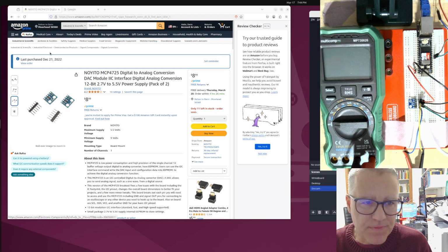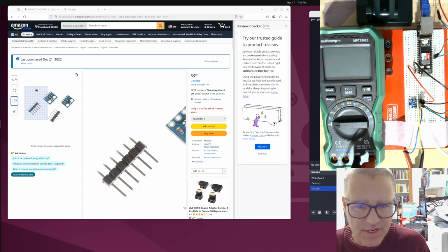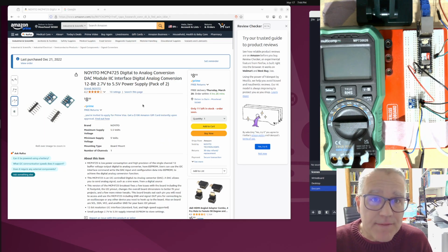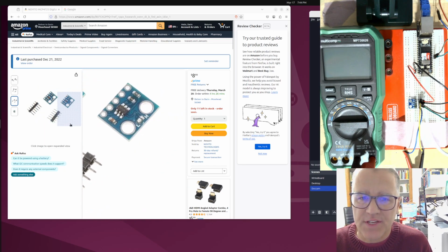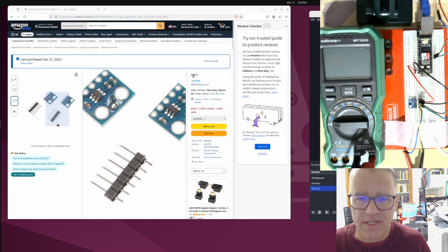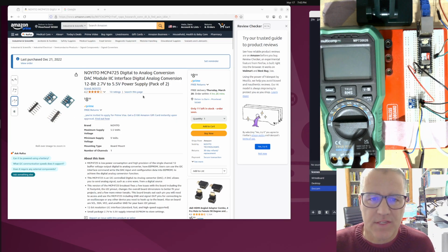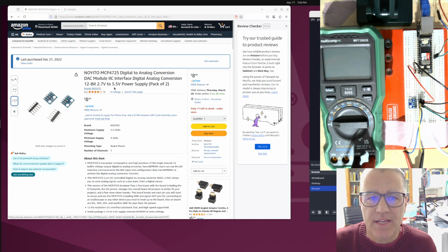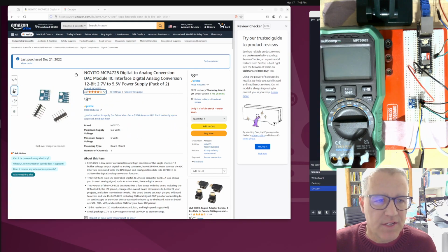Okay, so the chip that I showed you there on the camera, which you couldn't surely see, is a very inexpensive chip. I must say that for me, and of course I had to solder this myself, so maybe I caused damage there, one of the chips did not work, and the other one worked fine. It's a pretty versatile chip in terms of input supply. We're going to be supplying it with nominally 5 volts, actually 4.9 volts, but it would also work down to 2.7 volts. So a good chip in that regard.